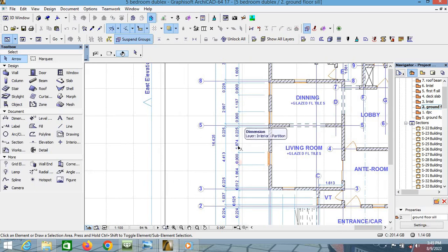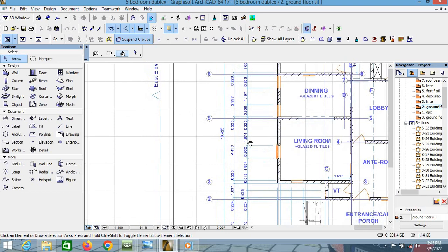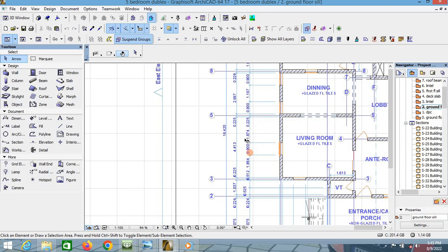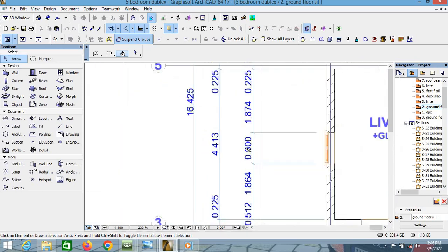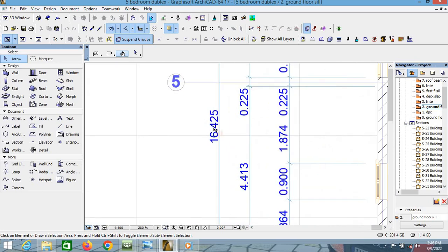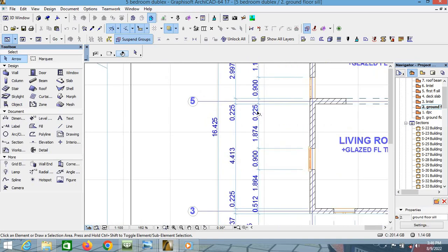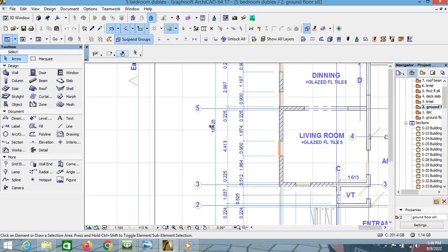But if you are doing, should I say, your building formwork, you are forming your walls, whenever you are trying to set out or form your block walls, you tend to use your wall to wall dimensioning. But when it comes to where you need to insert your windows and doors, for you to know the measurement of the windows, you take a look at the first layer. And then the last layer is the overall dimension, the sum total of the first and second layer.